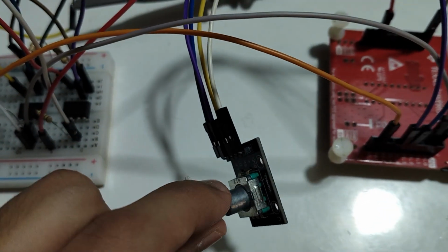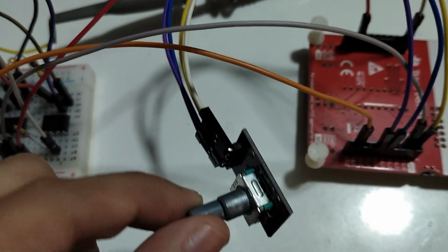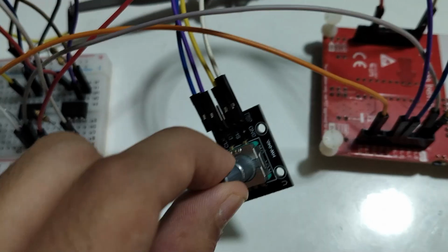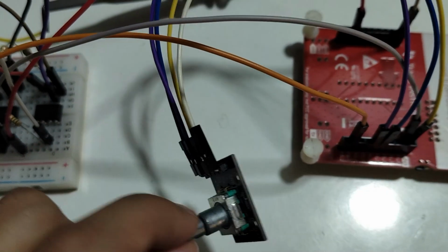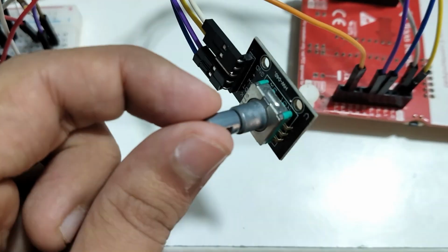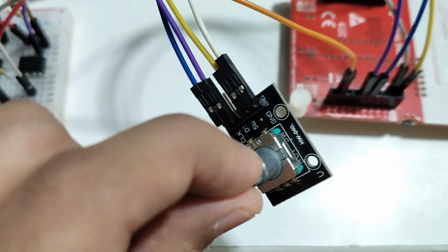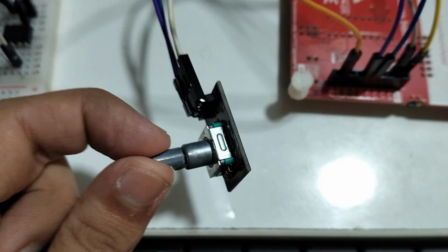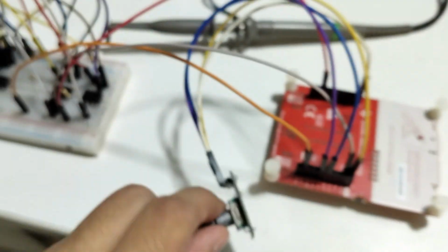But this doesn't really vary voltage. It sends pulses, and you can detect which direction it's moving in, and you realize it in your code. So it's much better than a pot, in the sense that it's not really affected by temperature and other conditions, since it's not literally varying the voltage. You are seeing that it's varying the voltage. So yeah, the rotary encoder is there, so you need to implement the code for this too.